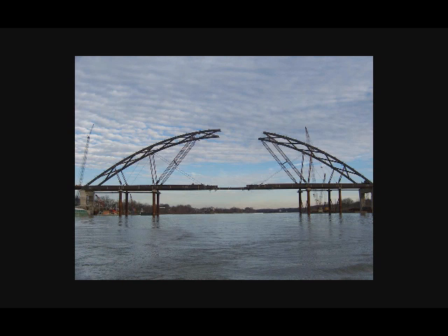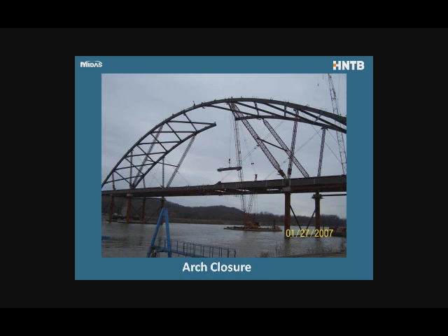In this case, the contractors made sure it would by building one of the arch halves about 6 inches off the center, moved towards the abutment. So there was a planned 6-inch gap. And they had a longitudinal jacking system. There were sliding pads underneath the supports where the arch is sitting on the caissons. And so to close the tie girder, they pushed the arch together until the last tie girder element would fit.